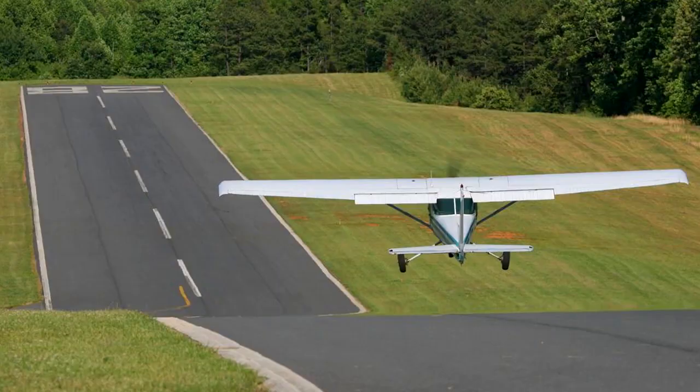The slope at some airfields means that the landing may only be possible in one direction. These are called unidirectional runways. Treat these runways with extra caution and always check that the current wind velocity will still allow a safe landing, since you may be forced to land with a tailwind. Although it will be made clear later, the landing regulations state that upslopes are not to be considered when calculating the landing distance, since upslopes will help to reduce the landing distance.